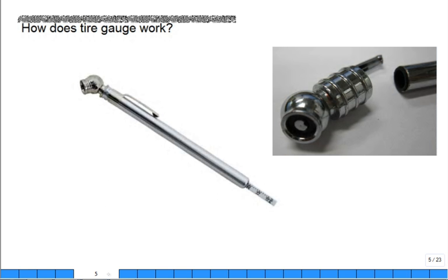And so in the front part, the cap part, you put in the stem. And right in that region there's a little rubber seal. Actually, it's now gone. There was one at the 9 o'clock. I'll pass this around. And it's supposed to seal it. And in the middle, the shiny part depresses the valve to let some of the air out of the tire and into the gauge.